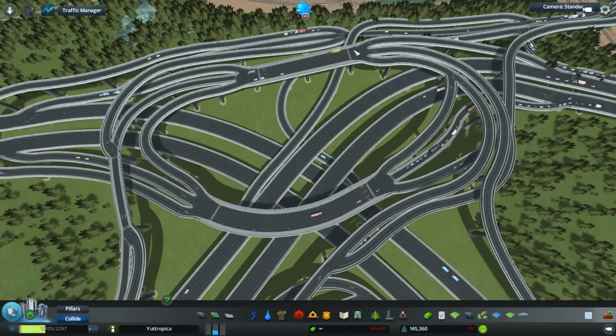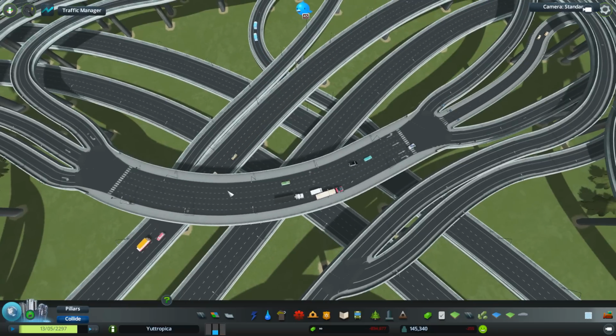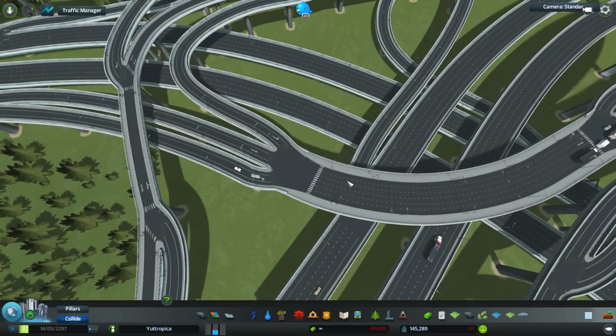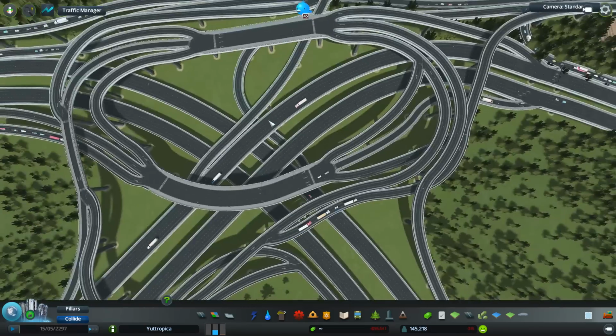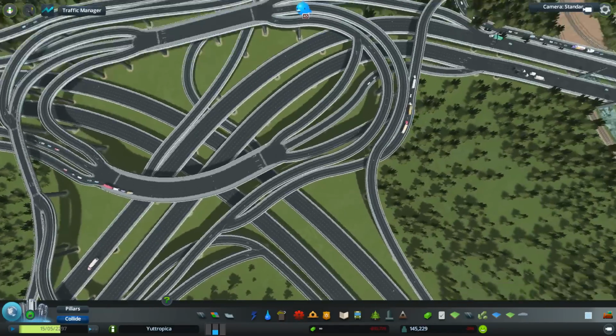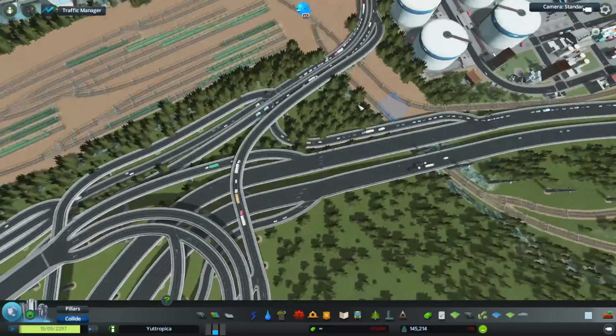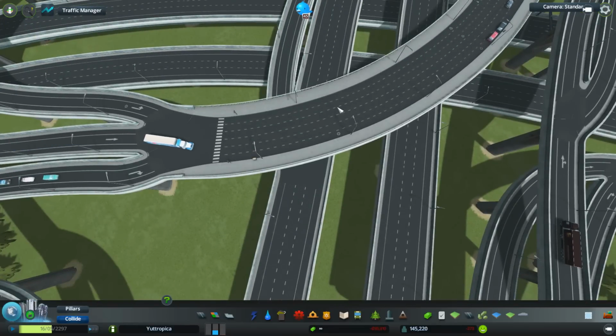one stretch of road that connects all the thoroughfares and then splits them off again, I decided to widen up the 3-laner to a 6-laner, even though this is just a regular avenue. The 6-laner really helps, since we have 3 lanes of traffic, and they could be weaving in and out, say this side, which is coming from this direction, but they want to go maybe over here or back over to this industrial area over here. There could be a lot of weaving issues from this area right here.